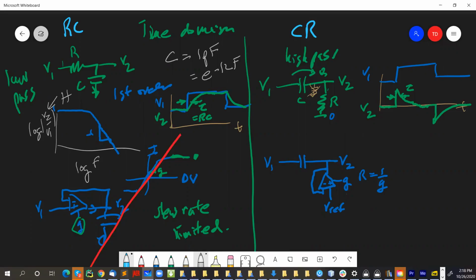Okay, so that's really all it's all about. Now, the rest of this is all just mathematics, working out how you get this behavior quantitatively, and how you compute the frequency domain response. And I haven't shown you yet the equivalent frequency domain response for the high-pass filter. Right, so let's draw it over here. This blue here represents the frequency domain transfer function, the H, for the low-pass filter. What do you think it looks like for the high-pass filter, the CR high-pass?